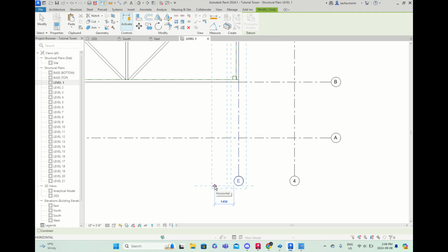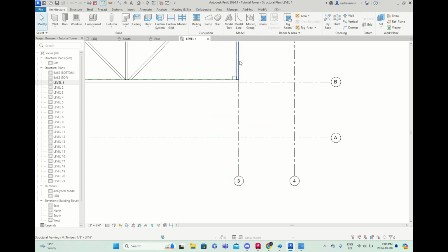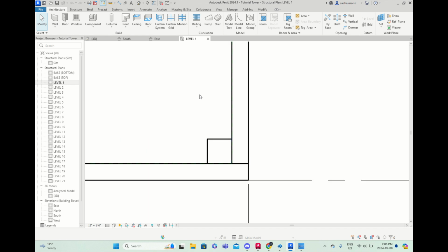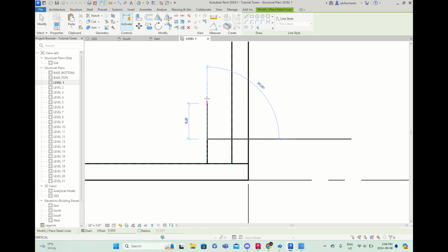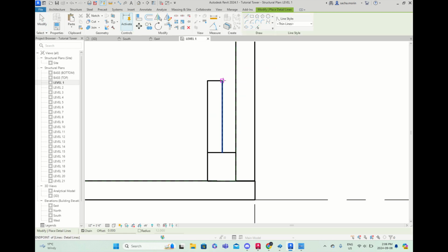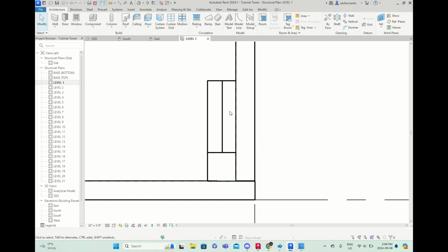Now, where do we want to make this grid line? It has to be at the center of our brace. So actually, before making it, I'll show you where that has to be. So, design line. Our braces will look something like this. You'll have one brace on the interior side of the column and one brace on the exterior of the column. Each of them is going to be half the width of the column, so 3/32 of an inch each, as opposed to the 3/16 that the column is.